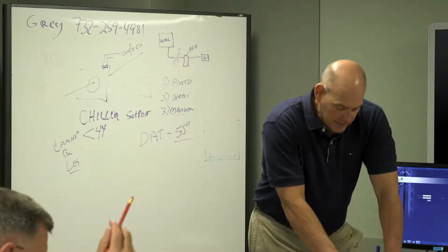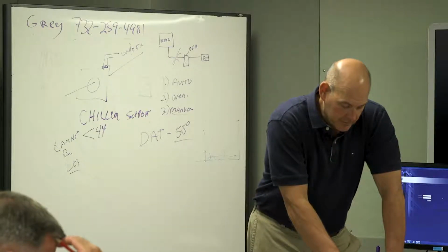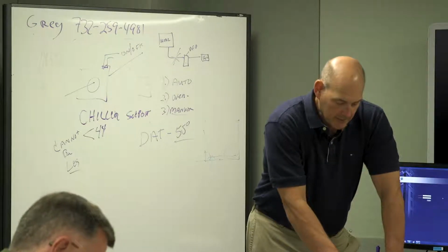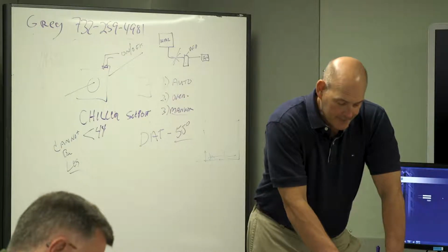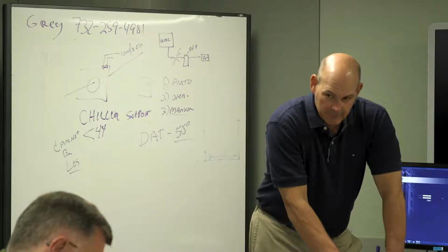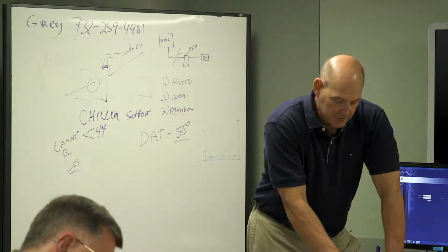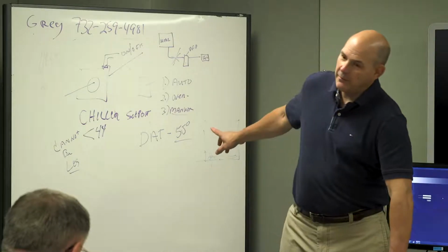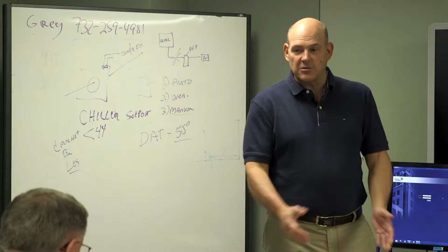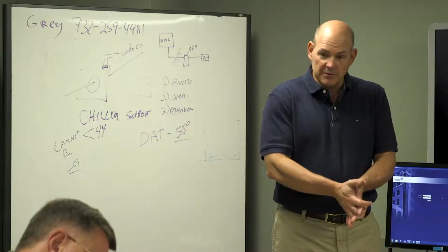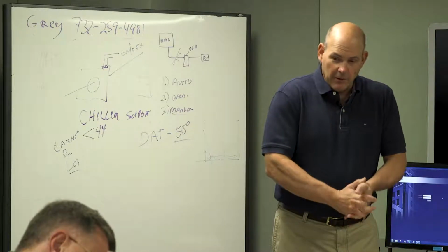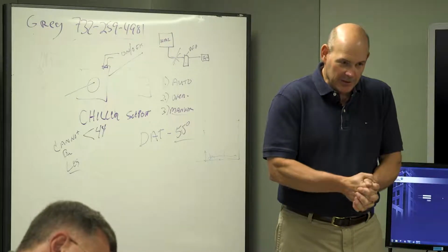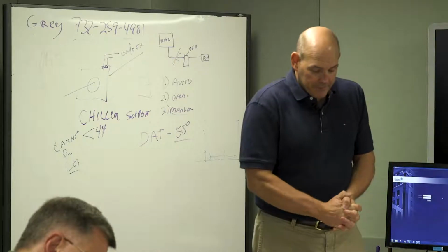So then the next point is the chilled water temperature, discharge of the chiller. CH3-CHWS-T. T, what is it? T is for temperature. So that's the temperature reading. It would be an analog input, and that's going to tell you what the temperature is. Yes, it's a temperature sensor. All right? Now I'm going through this, and you might write this down. You're going to find it redundant, but the answers are all on the page.